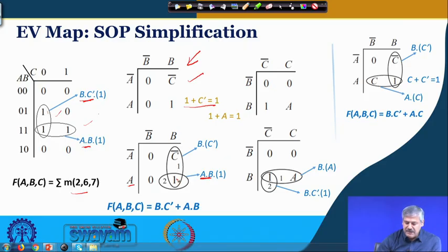So, there is a hidden implicit C prime here without making any difference in the meaning of the entered value. This C prime and this C prime can be combined together, for which B is remaining constant with a value B, and the variable that is entering, we simply AND it with the value that is remaining constant, which is B here. So, B C prime is the corresponding term that is getting generated.